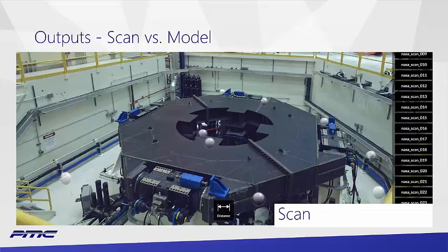Most projects, you're going to need to develop some or all of the point cloud into CAD so that it can be worked on by your designers and engineers to produce bid documents or construction documents down the way. Some extremely sophisticated customers can use the scan intermixed with some CAD or BIM data, but in general you're going to be doing BIM or CAD derivative work from the scan, and this is a very manual process. There are tools out there that are semi-automated, but there's nothing that will simply convert scan data into a Revit model or AutoCAD model.